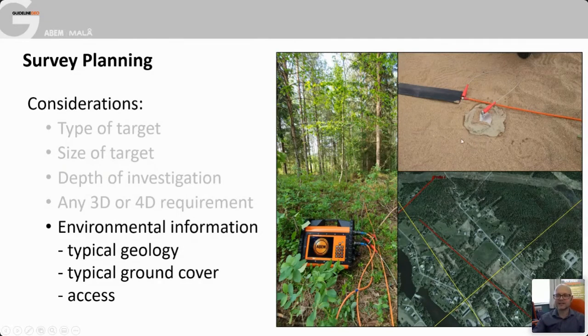So this image has actually come from a customer this week. They were measuring over sand that was on top of some concrete reinforcement at the back of a beach. And so they needed to be able to somehow get the current into that. Couldn't use traditional electrodes. What they've done here, scrape the sand away, put a bed of clay and then a flat plate electrode over the top. So by knowing what the geology, or here the man-made situation was, they could prepare before they left the site.